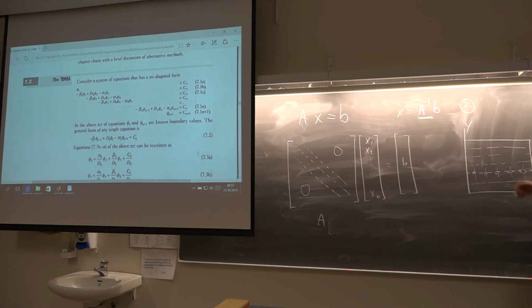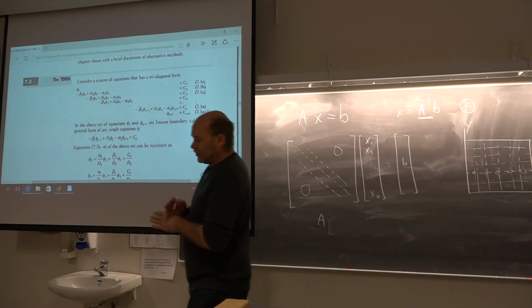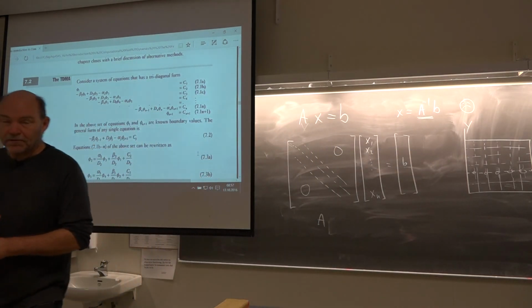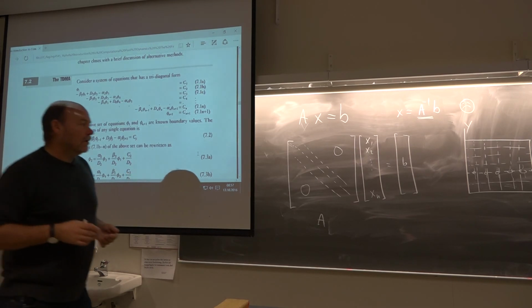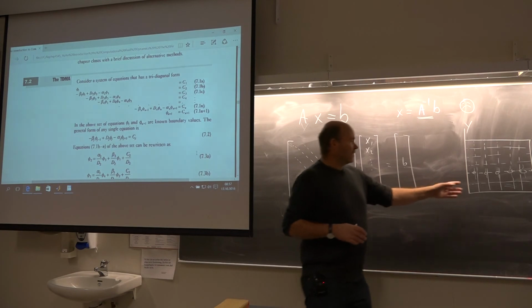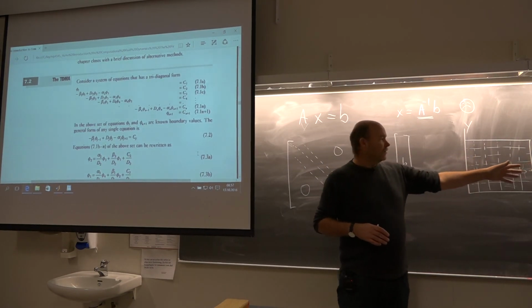What you should also do is use lines in the other direction as well. These are alternating direction implicit, ADI, methods, quite popular, and that will ensure that you actually get a solution, because this is a little bit dependent on your geometry, if delta x is bigger than delta y, and what the flow direction is.